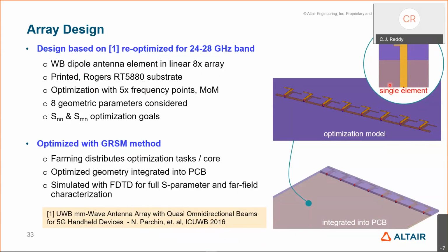One of the advantages we have is that we can start this design with, let's say, a 2.5D solution. When we say that, the substrates are not discretized, so it is an infinite substrate, but then you discretize only these metallic elements, so your computational cost is very, very low. So it lends itself very well to very quick optimization of your array.